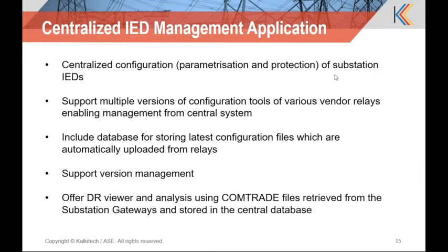So centralized configuration management is available for managing multiple substation IEDs and multiple versions of the configuration tool. This is a major headache for the utilities: how to manage multiple versions of the tool. In a substation installation there can be multiple versions of the same vendor's relay, and multiple versions of the tool need to be used to configure specific relays. These are not installable on a single machine itself, so multiple scenarios need to be used. All this congestion needs to be avoided.